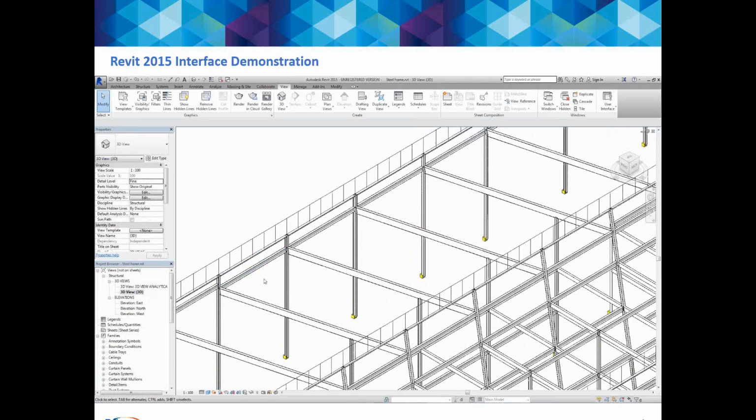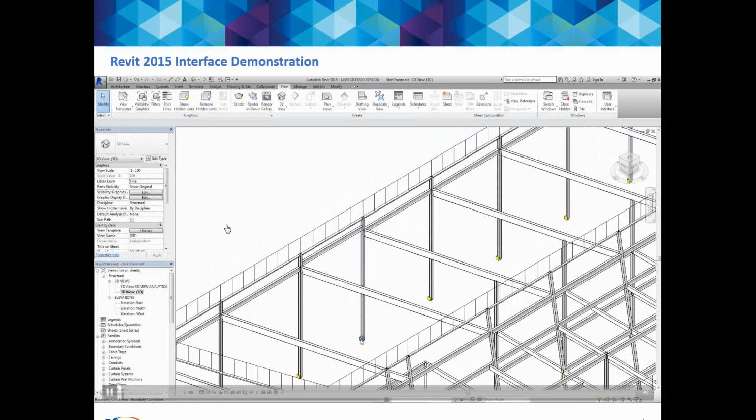Since there is a little time lag with sharing the screen, I will wait a little time so that you can see the video file. So in the Revit structure model, we can check their section size or boundary conditions and loading input status.